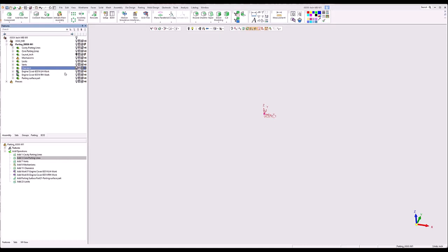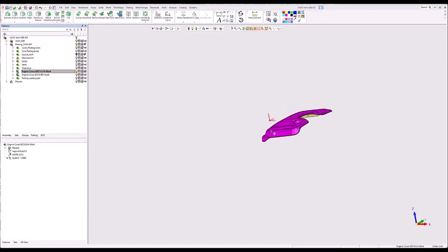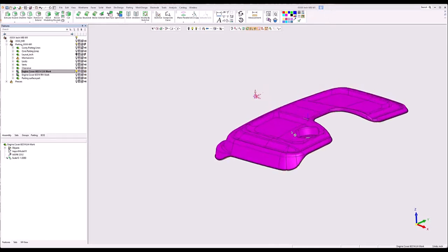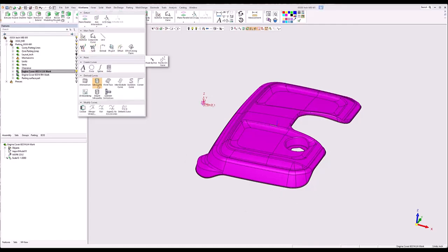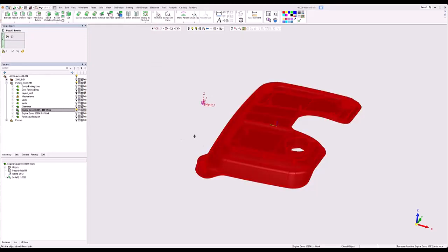Before I get into creating the clearance, I'd like to create a curve around each part that represents the periphery of it, and that I can utilize in some of these other parts, and for ease of picking just one curve rather than making a composite all the way around the part. To do this, I'll use Object Silhouette. So I pick the part. I'm going to change the tolerance up a bit to 10 thou, I don't need a perfect curve, I just want a good representation.